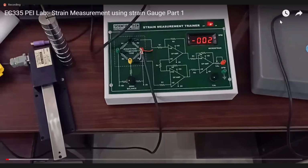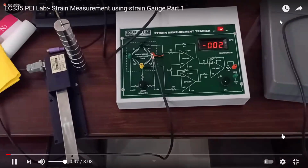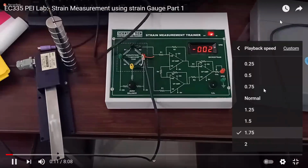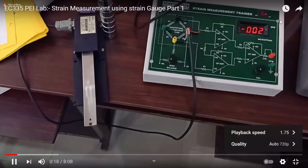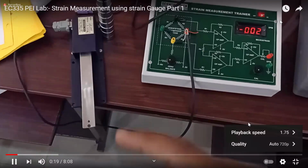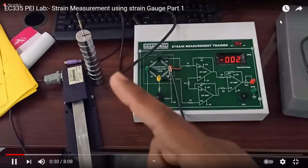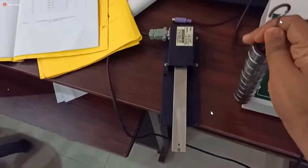A strain measurement using a strain gauge. Okay, so this is the instrument that we'll be using to measure strain. So first of all, we have to calibrate this instrument such that it gives the correct reading. So here we are having a strain gauge. Okay, this is the load that we'll apply. Each cylinder is of 100 gram weight and the total weight is 1 kg. So we will take this thing here. So he is applying that load on the strain gauge.